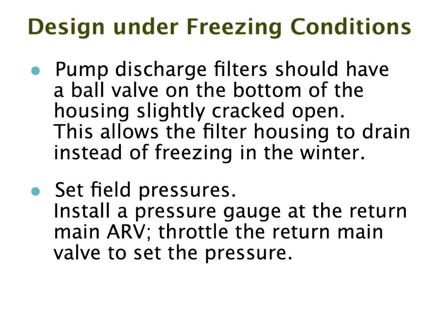Okay. Pump discharge filter should have a ball valve at the bottom of the housing slightly cracked open. Okay, this means that the filter housing can drain instead of freezing. Again, that's if your filter housing is out in the field and not in the cellar of the house or somewhere that's kept warm, which it sometimes is. Set your field pressures and install a pressure gauge on the return main air vacuum relief valve, which is where I spoke where you have a Schrader valve, and throttle the return main valve to set the pressure.